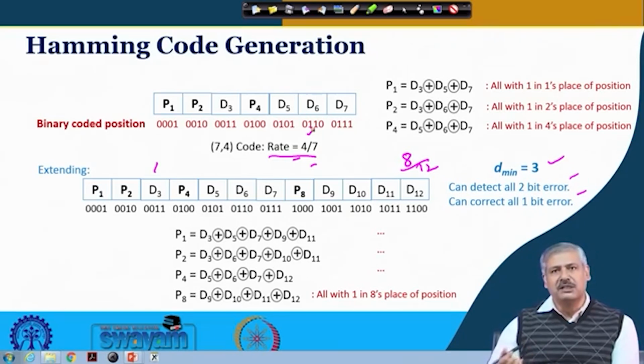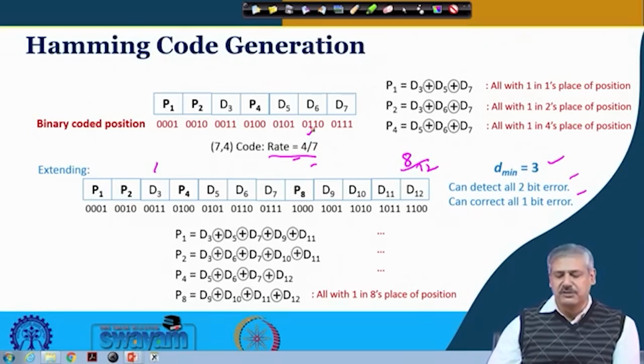This is one thing we need to take into account: to get some benefit out of this kind of methodology, there is some cost associated. This cost is additional bits that need to be sent along, which will bring down the effective data rate, the effective transmission rate.